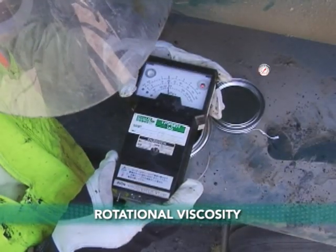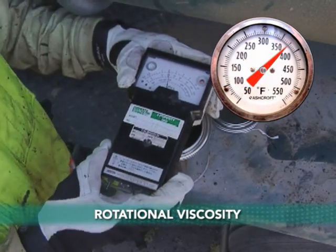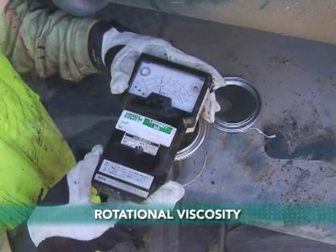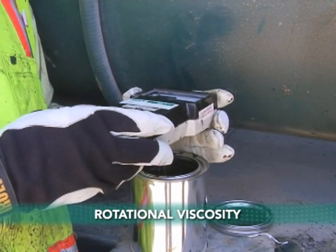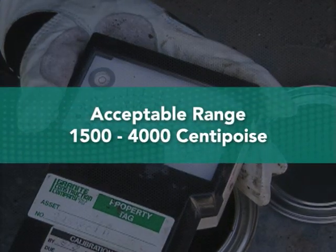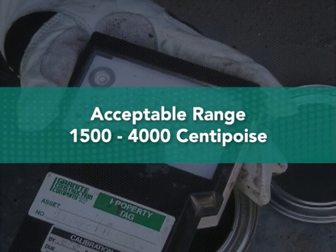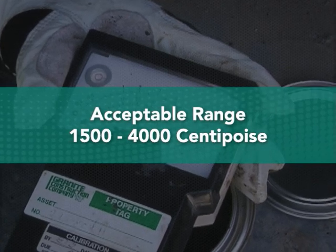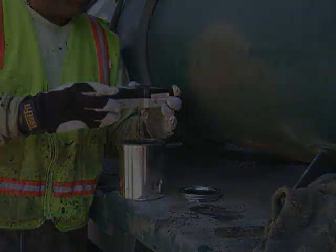This test must be conducted at 375 degrees and gives an indication of fluid consistency of the asphalt binder. It monitors pumpability to identify changes which might affect hot mix placement and compaction. An acceptable range for asphalt rubber binders used in HMA is 1,500 to 4,000 centipoise. Typically, this test is conducted on an hourly basis.